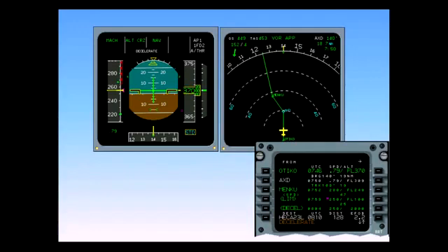The aircraft has just overflown the top of descent. The FMA displays the message decelerate. The suggestion is to select the lower speed since the aircraft will be above the descent profile. The aircraft vertical position versus the descent path is indicated by the vertical deviation VDEV symbol along the altitude scale. You can see that the aircraft is approximately 300 feet above path.